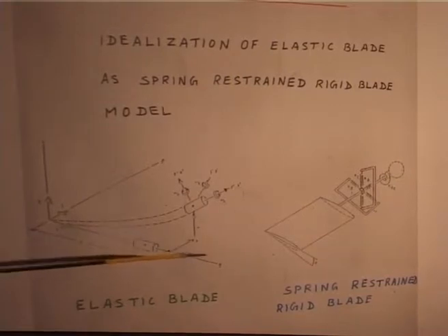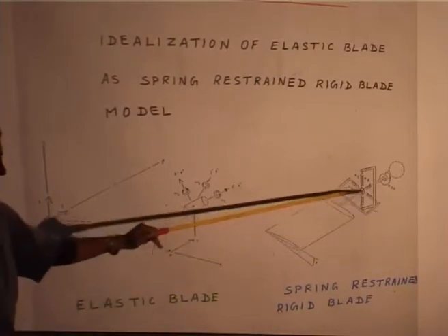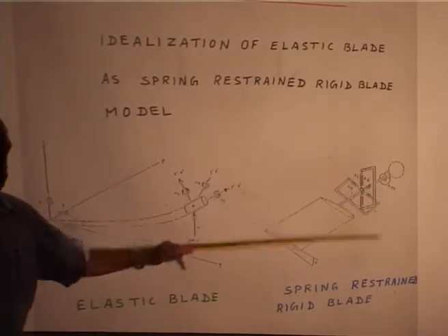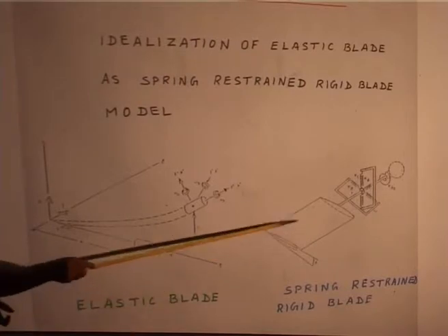You are representing only one flap frequency because there is a flap spring, then there is a lead lag spring, one torsion. So, you will have 3 frequencies, that is all, and the blade is a rigid straight blade. Okay. So, you can get certain phenomena reasonably correct, but you can't get the vibration and other things because this is not a true representation.